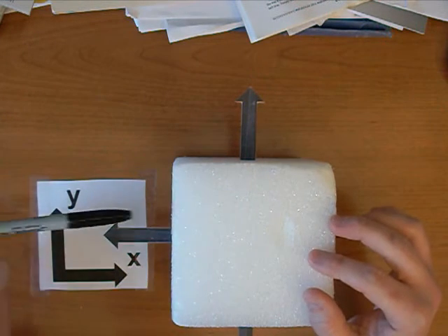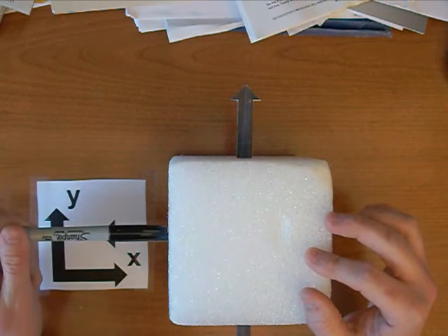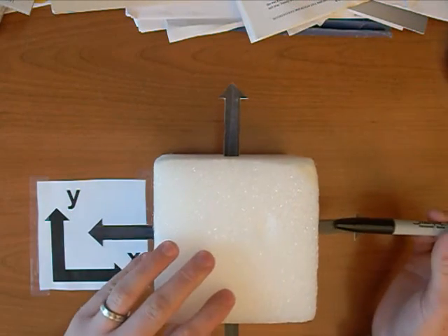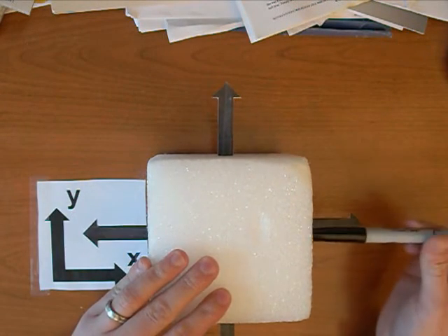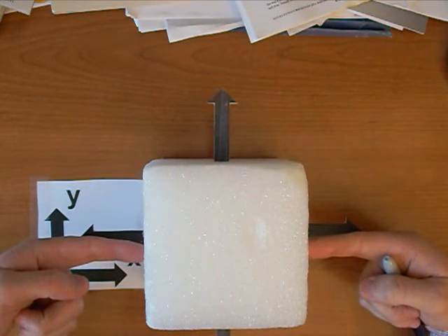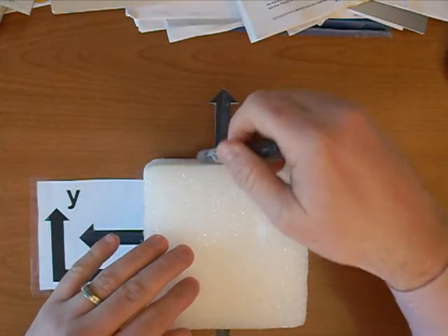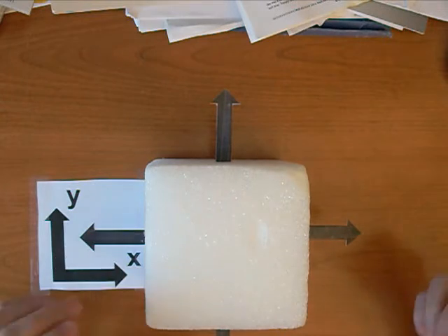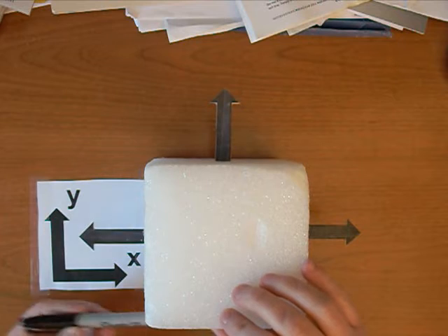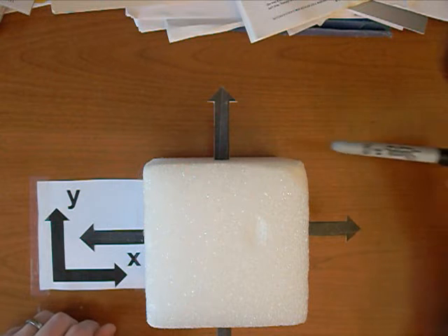So this pressure is going to have an arrow going into this face right here because it's opposite of this unit outward normal for this surface area. And therefore on the other side as well, it's going to be acting opposite of this unit outward normal. So both arrows are going to be pointing like this for the pressures. So that's our pressures. For our shear stresses, which act on this face right here and this one right here, if you remember in the drawing, the shear stress acting on this bottom face is pointing in this direction right here, and on the top face it is pointing in the other direction.